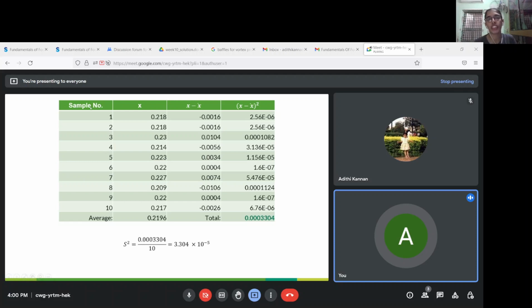So if you have, let's say, a time t equal to 20 minutes, you are taking 5 samples. So then your n will be equal to 5. You will perform the same kind of calculation to find out your s square at 20 minutes. So for an unmixed solution, S naught square can be given as P into 1 minus P. So P is your fractional component of the active ingredient that you're looking for.